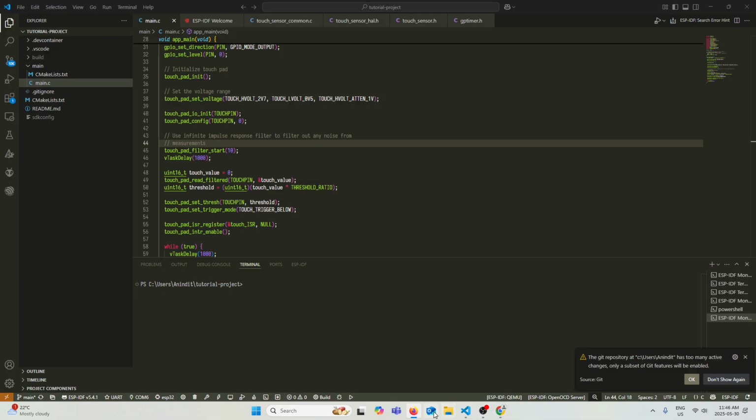All right, so I guess to summarize, the way ADCs work is essentially that the ADC will sample at a certain frequency. That frequency, of course, needs to be a Shannon-Nyquist frequency. So that means either 2 times the bandwidth in the frequency domain, or 2 times the highest frequency component in the frequency domain.